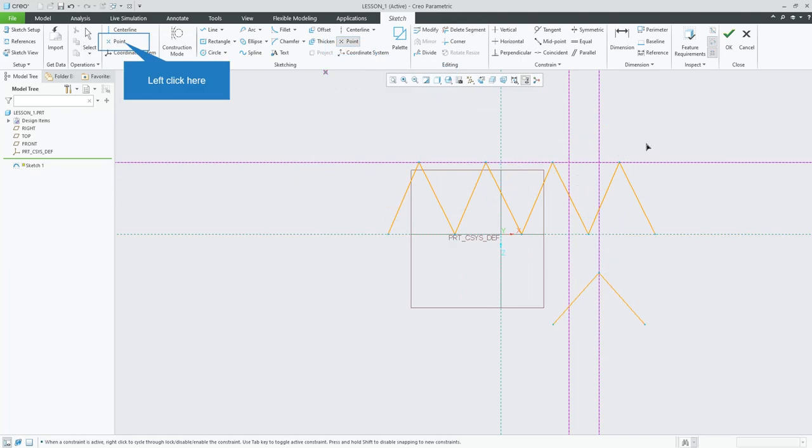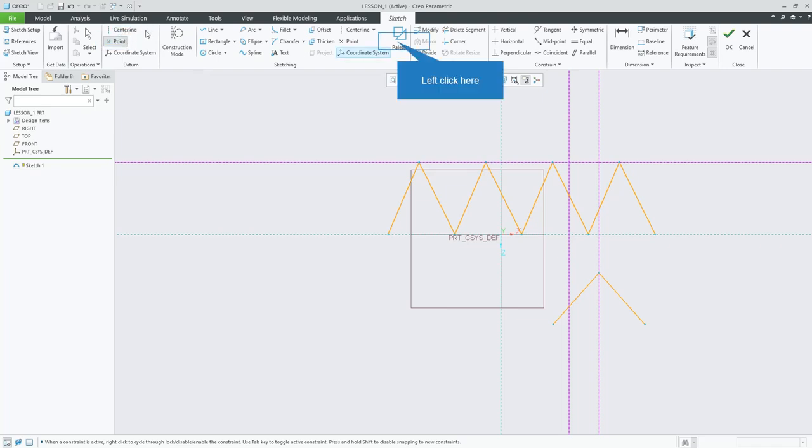Points. Points are good for placement. They're construction only. They won't show up throughout the sketch. These points over here will show up outside of the sketch. These axis lines over here will show up as axes inside your part if it's in a sketch. So you've got to be kind of careful about these on your sketches, that you don't use these if you don't have to, or unless you really mean to.